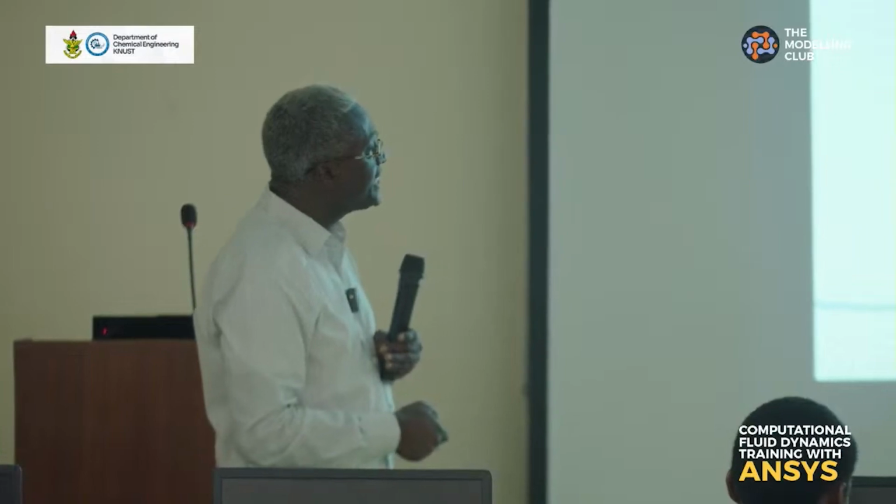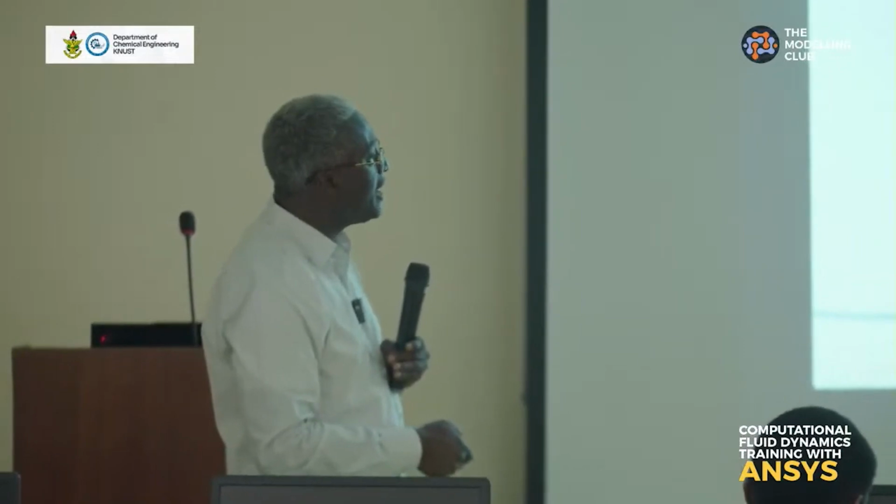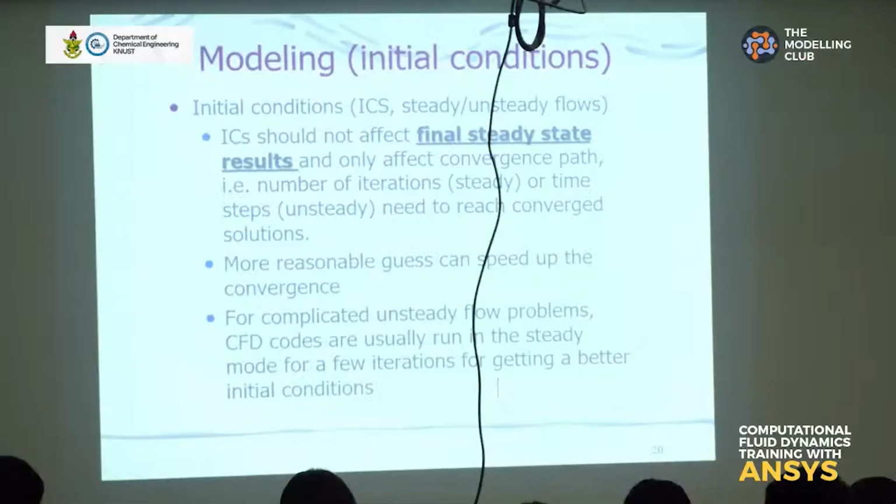Now, for complicated unsteady flow problems, CFD codes are really run in the steady mode for a few iterations for getting better initial conditions.